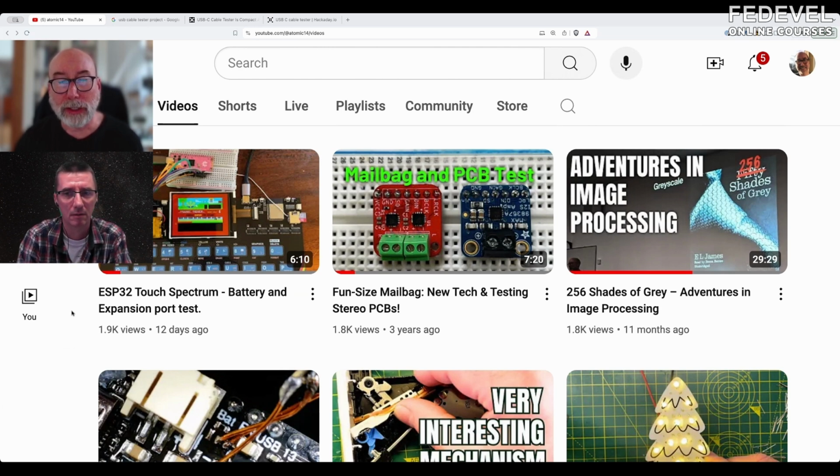So what you do is you send some high resolution artwork. I send a transparent PDF, and you send instructions on where to place it. My approach has been to take the size of the PCB and create an image that is exactly the same aspect ratio but high resolution, and then just tell them to draw it on top of the whole PCB. They were suggesting that you should send instructions on the positioning, and I thought that's going to cause lots of mistakes. So you just draw the board outline, and then put this image on the board.